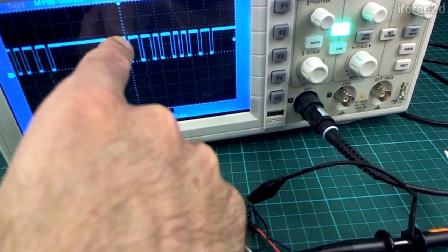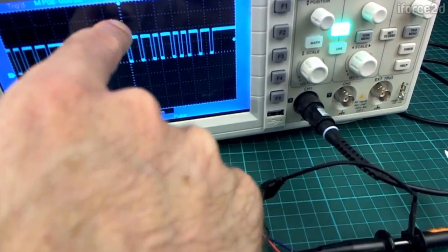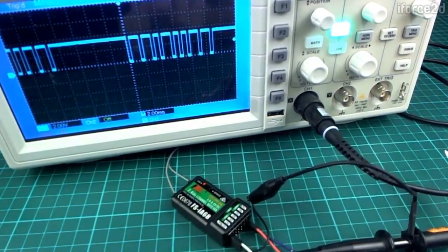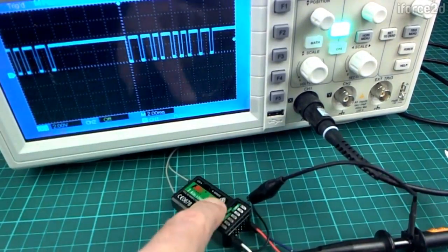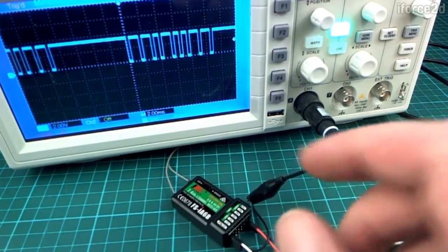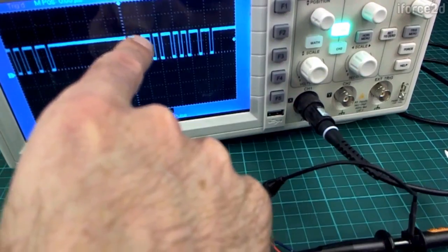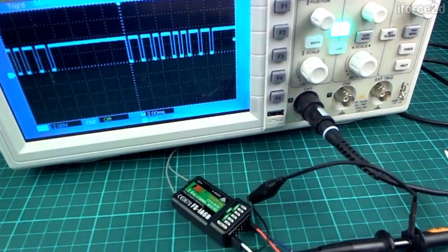So it counts up how many microseconds have passed between this point and that point. So it can happen that the clock on this side and the clock on the receiving side are not running at exactly the same rate, so you won't get exactly the same number coming out the other end of the transmission. So that's one limitation.